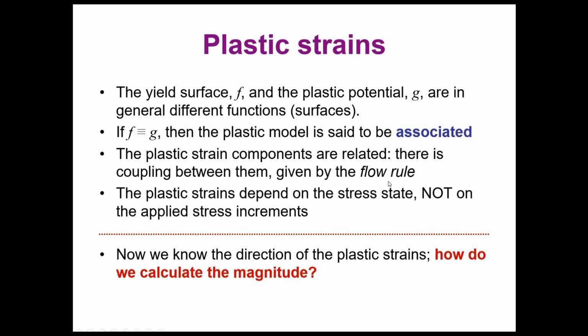But this direction and this value of the plastic deformation, we have two components, the axial component and the shear component, so they are related, they are not decoupled as in the case of the isotropic linear elasticity. So the plastic strain depends on the stress state, not on the applied stress increments.